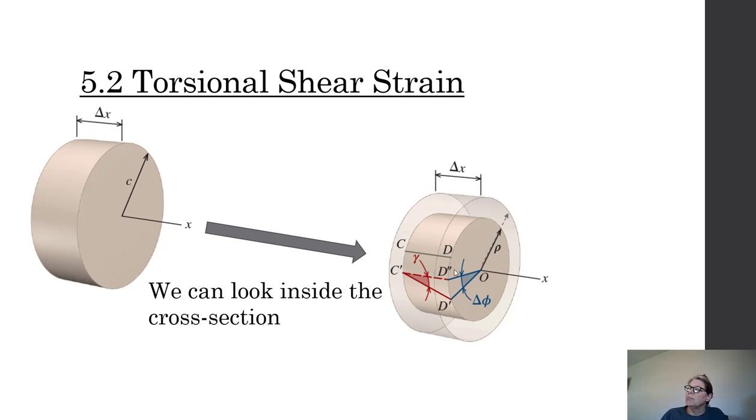So as we are moving along rho, we're going to find that the strain is also increasing. And if the strain's increasing, our stress is increasing. Because as I twist, we're twisting right around that centroid, which means there's no twisting action right at that centroid. But as we move away from the centroid, we're having to twist farther and farther to keep the material together.